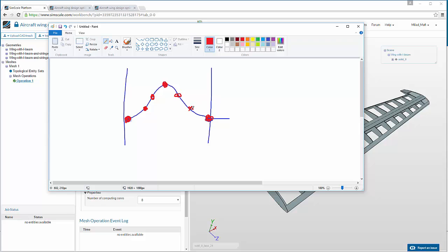And just by this higher number of points, your simulation, or your mesh, will be able to really, let's say, cover all changes fine. But there's also another possibility. Let's remove all these points. And just imagine you would use a second order function instead of a first order function.